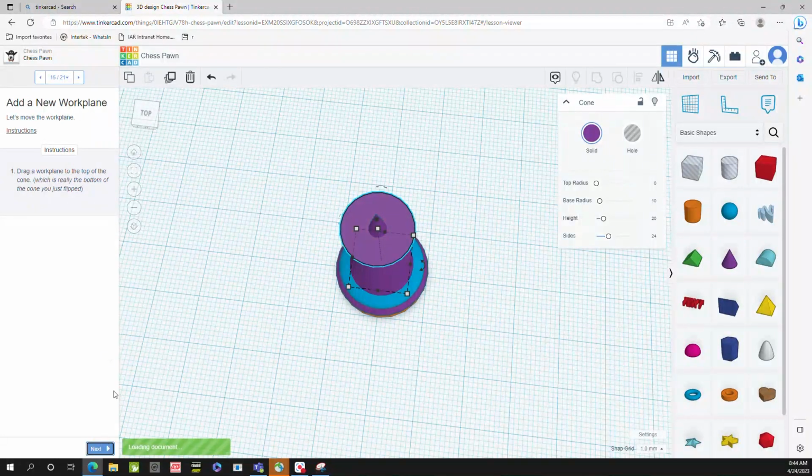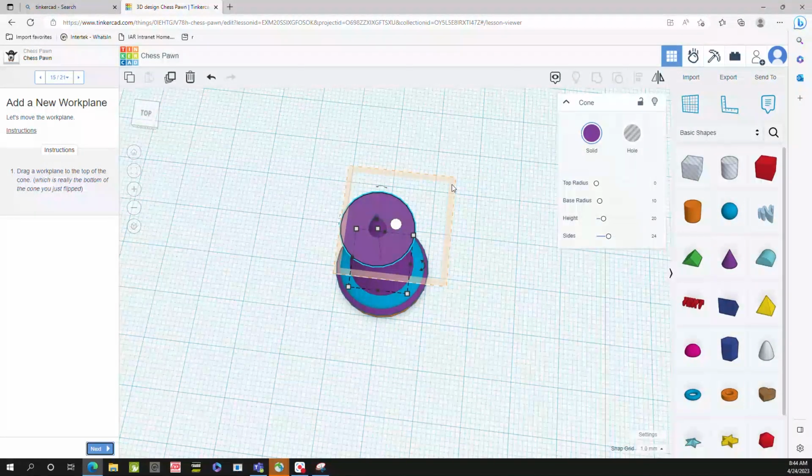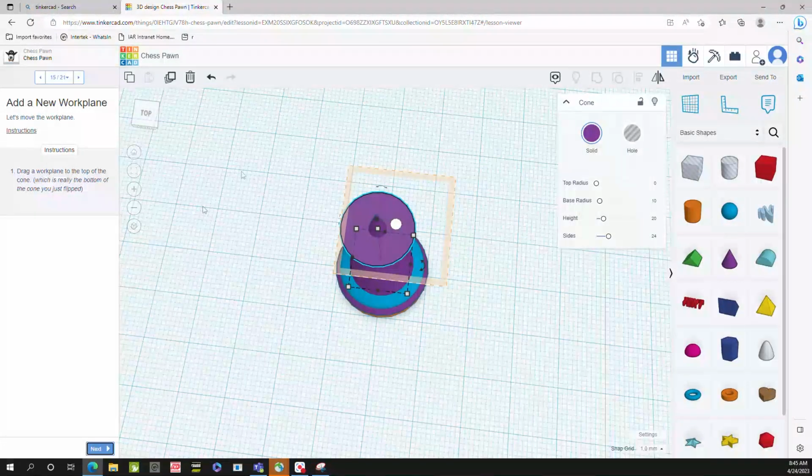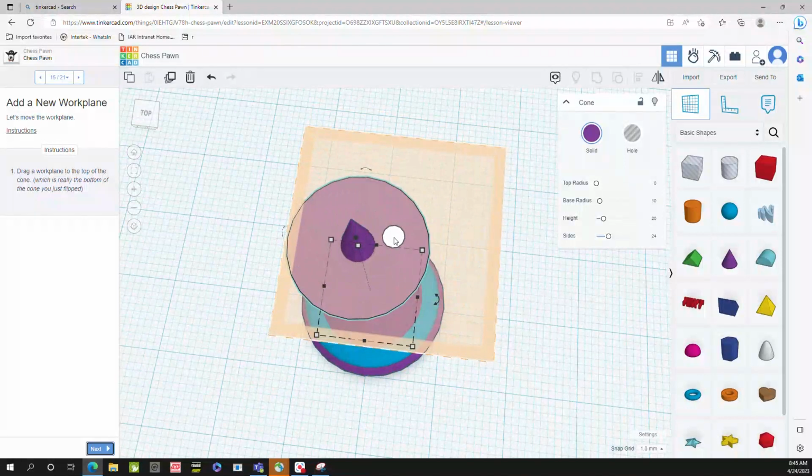Alright, we did the second step. Now we have to get another work plane on top, but I haven't been using the work planes very often. What I'm doing is moving the parts and typing how much distance I want with respect to the base plane, the bottom plane. But anyway, let's do a work plane where by typing W, you go there